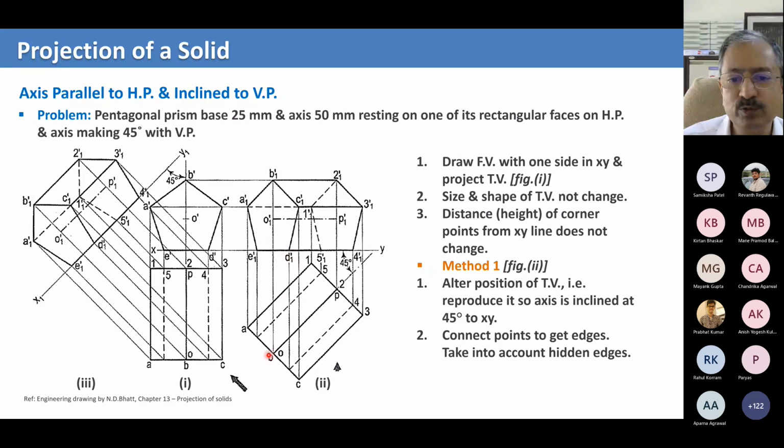So if you see from the top view here, just look at the last picture, look at the A, C. It doesn't matter. This whole thing. The outermost rectangle here is nothing but the total projection of the object, which includes three projections. Of course, we are seeing from the top view, so actually we are seeing the projection of the top two faces. What it contains is this line in the middle, which is nothing but the top line of this pentagonal prism, right? And what you're seeing as the two rectangles on two sides.